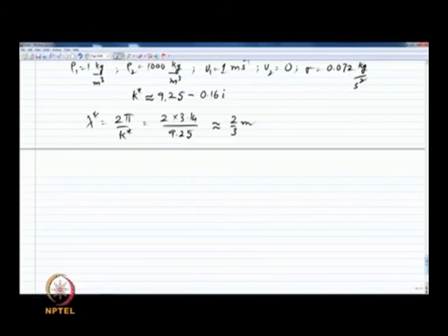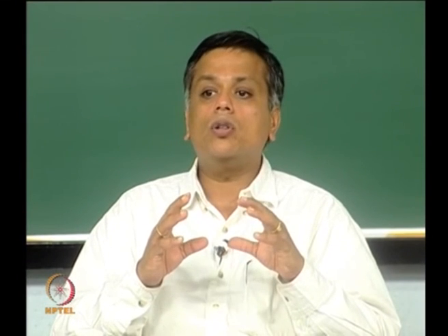So, the objective of this linear instability analysis is to get to this dispersion relation and then use it to find k star and k n as functions of the flow quantities. So, this is essentially the utility of linear instability analysis. And I also know the range of the one wavelength that will dominate the process. So, given this, it is like characterizing the natural response of that system.